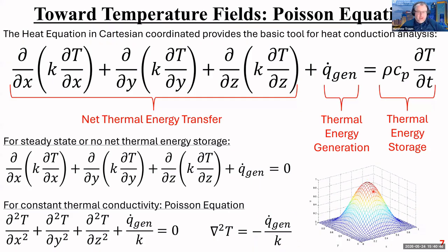So I'm basically just generating thermal energy here, and then it's conducting down and out as the temperature drops down and out to the edges of my object, right? This would be like a square plate that's hot in the middle, maintained that way by some sort of external heat transfer or energy generation, and then the heat's just dissipating out in all 4 directions.